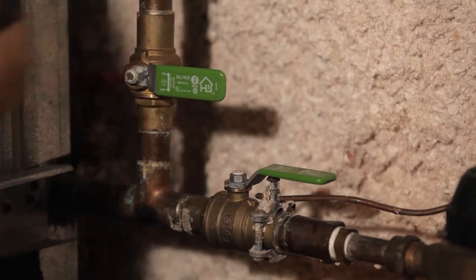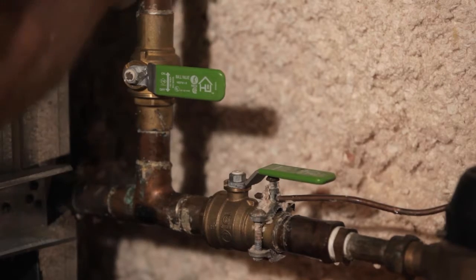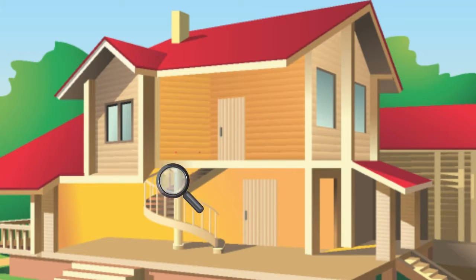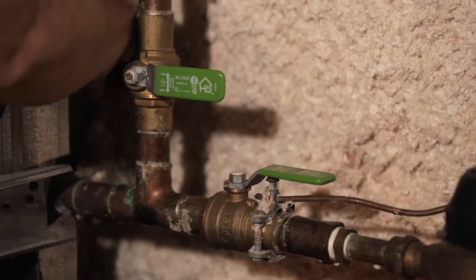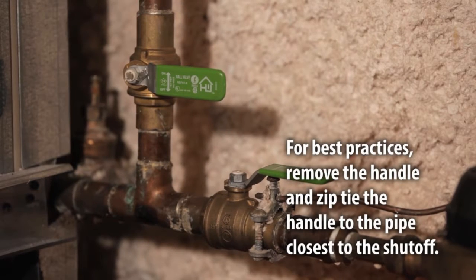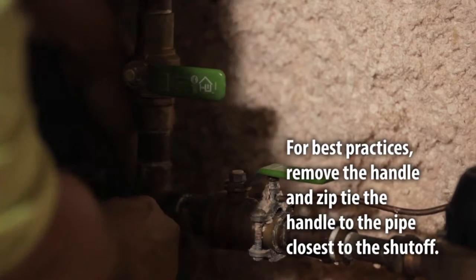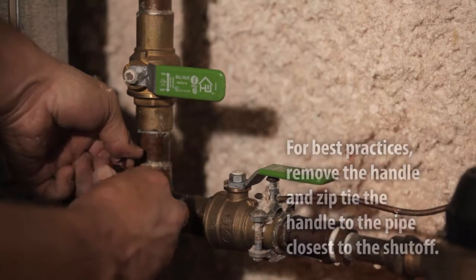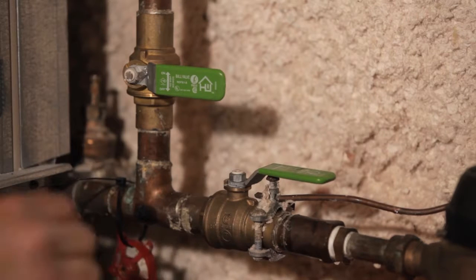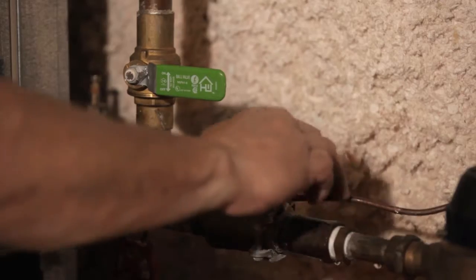First, you will zip tie the main water shutoff valve in the off position. In most cases, the shutoff valve will be located in the house, either in the basement, a crawl space, or somewhere on the first floor. If there is no main shutoff valve inside the house, you will need to shut the water off at the meter pit. Most shutoff valves in the meter pit will have a hole that lines up once in the off position. This is where the zip tie should go. If this hole is not present, you will need to run 2 zip ties diagonally across the shutoff valve, ensuring it cannot be moved back into the on position.